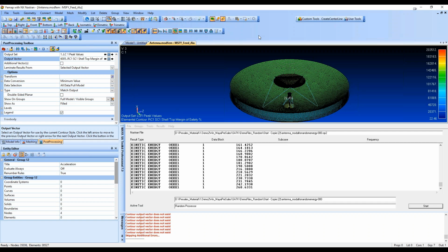Okay. So just to make sure I understand right now, in terms of what you'd like to see on top of this, is you'd like to be able to look at the forces in the elements, so either 2D elements or 1D elements, and be able to do the post processing yourself, or work it out in any customized way. Is that right? Yeah, I mean your stress margins, once you get familiar with it, they're probably fine. But we're going to want to look at the forces individually as well. Okay.